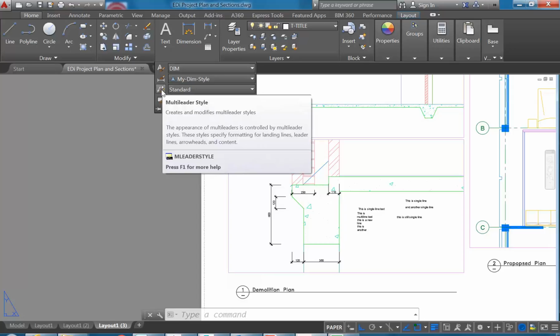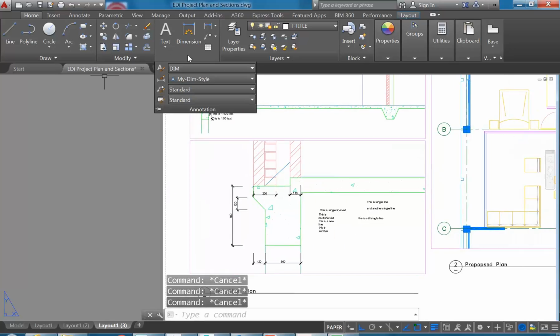Have any of you not used leaders in AutoCAD? Yeah, you might not have, because, I mean, with Revit, you've got the option just to add arrows to text, which is a great thing. But in AutoCAD, you don't have that, so you have to use this special leader option whenever you want to put arrows in. Or a lot of people I see just draw lines and draw their arrowheads manually whenever they need to do notes. But leaders are great when you get them working. It's just that they can be a bit fiddly to set up because annotative needs a bit more setting up with leaders. So I'll do this afterwards anyway. So I'll give you some time to try those things first.